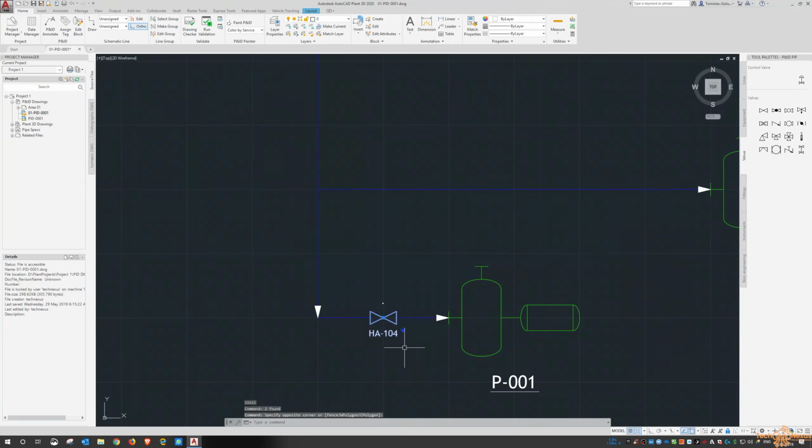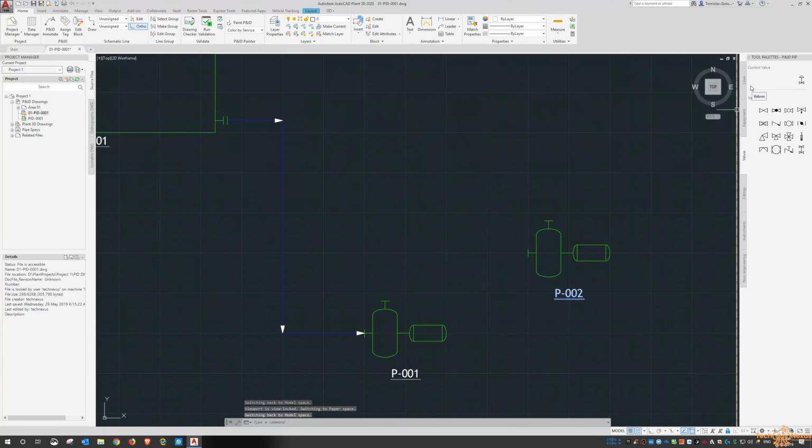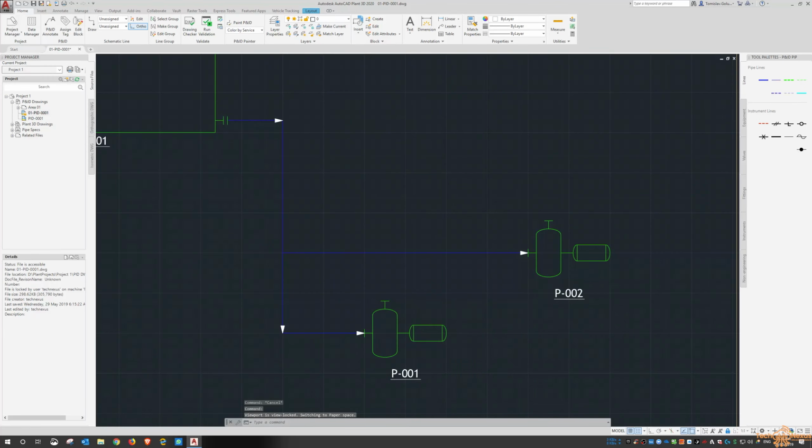You can do it if you really want to, but again, there's a lot of varying factors in there that might say, we're not going to bother, we're just going to keep them as headers and secondary. And you can see I've done that exact same thing I didn't want to do. So I'm just going to go back, do a line and click on it, and then go N for new, and then come back and run that line over. So now you can see we have the 2 line numbers there.